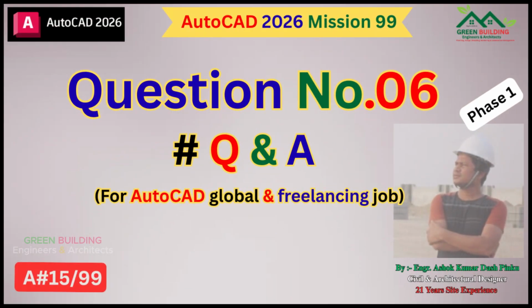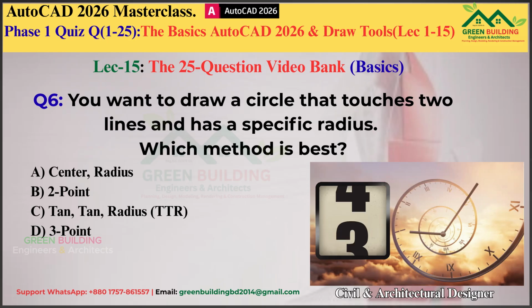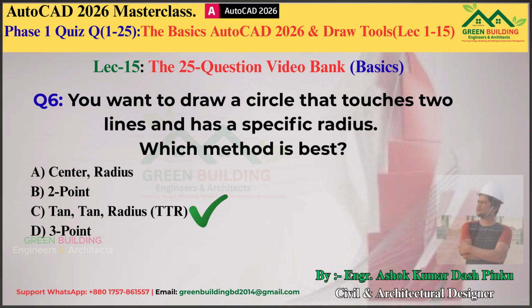Question number 6. You want to draw a circle that touches two lines and has a specific radius. Which method is best? Option A, center radius. Option B, 2 point. Option C, tan tan radius, TTR. Option D, 3 point. The correct answer is C.